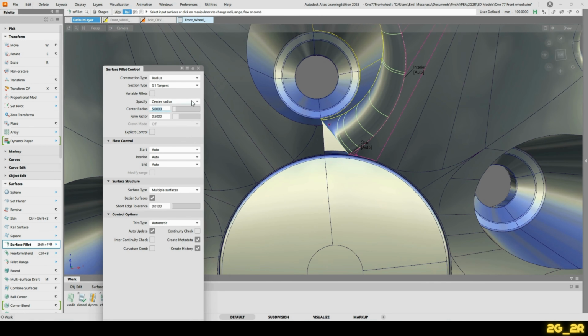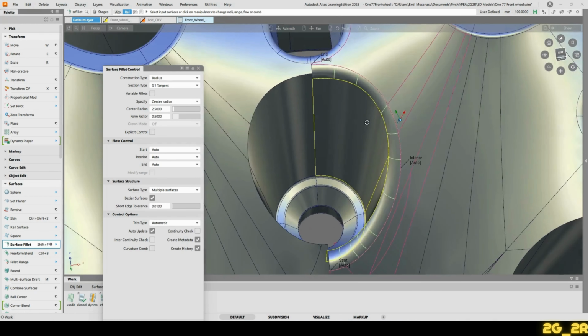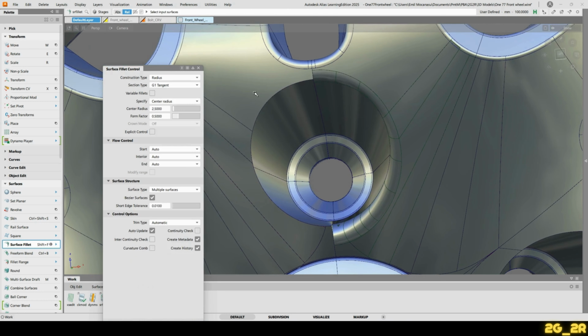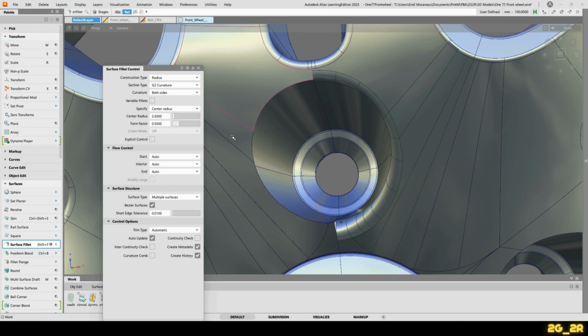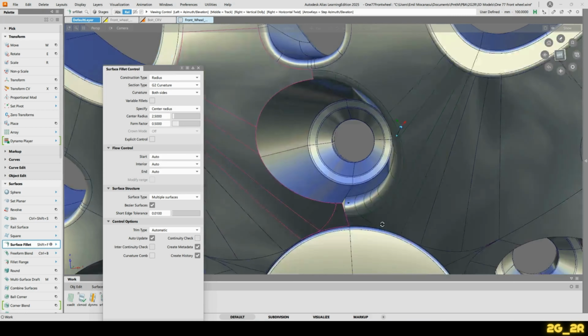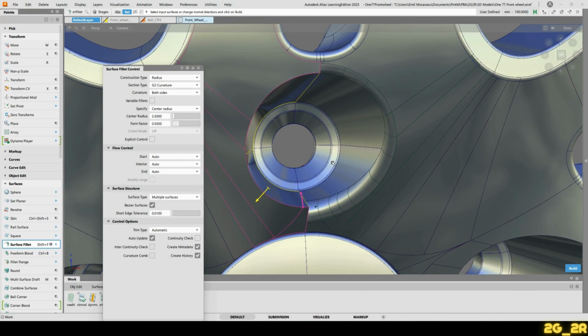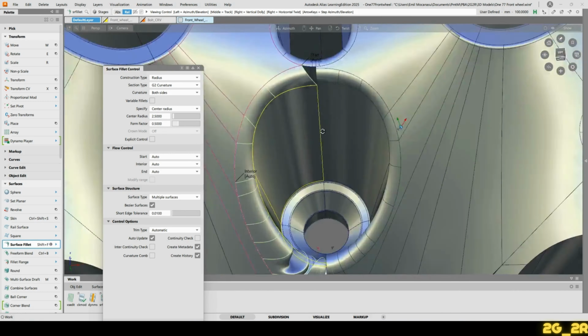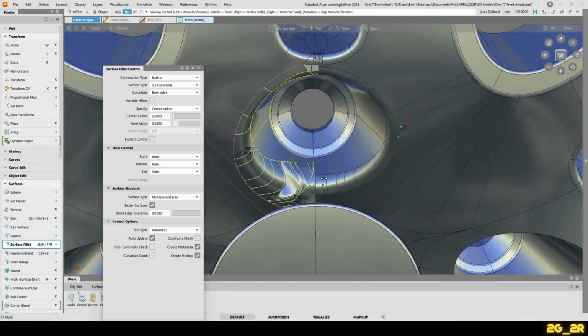So let's make the radius first smaller, let's say 2.5. And this gives us that. Perfect. Now I want to go the other way around here. I'll still stay with the radius, but I'll go G2 curvature, same size. And you'll be able to see the effects here. So you can see G2 eats away a lot more of that surface compared to G1.